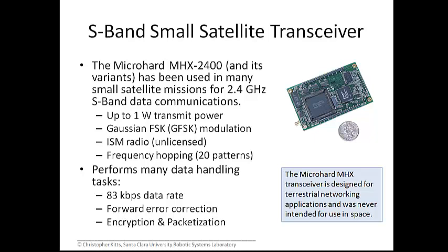As it turns out, we broadcast the results of this radio through an antenna system, a 3 meter parabolic dish that really focuses that energy. In the direction that the antenna is pointing, we actually blow the power spec for use of this in an unlicensed manner. Because we are using it through a very high gain dish antenna, we actually have to get a license for this. It no longer is a piece of unlicensed equipment, given the way we use it. And so we have a full-blown FCC license in order to use this particular unit with a 3 meter parabolic dish.